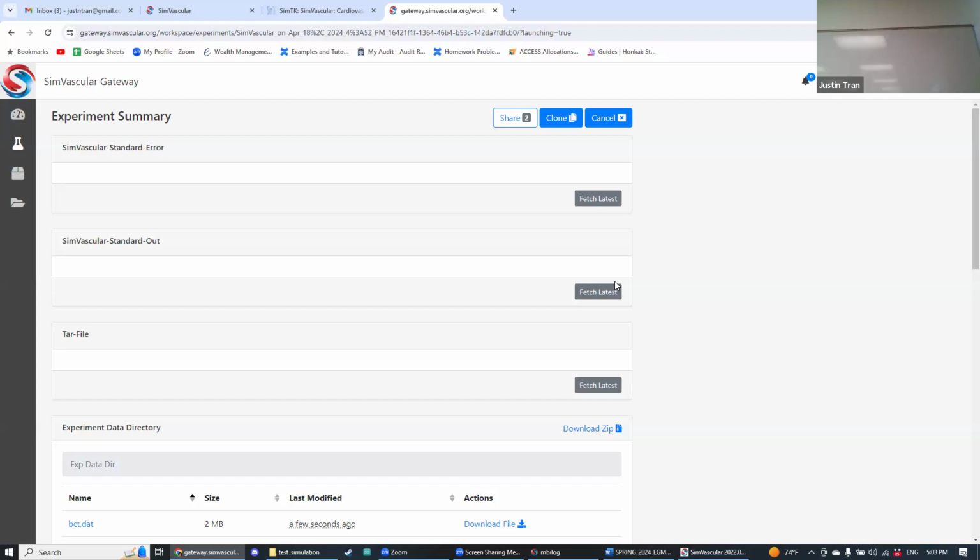It's tricky. I think your biggest hurdle is going to be just getting a mesh. I'm wondering if this might be causing the issue right there, because the model is kind of pinching in on itself a little bit. So when the mesher tries to mesh this, it may not be able to find an element to bridge just yet. Even though it's supposed to be all one solid model, you can see here there's a really tiny gap because of the pinching. Sometimes the smoothing is able to take care of that, so you can keep trying to smooth it. Let me go back here.